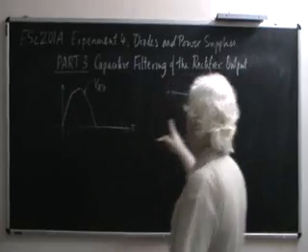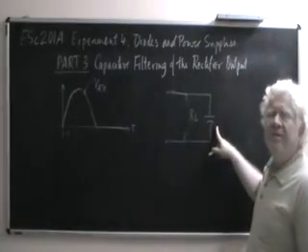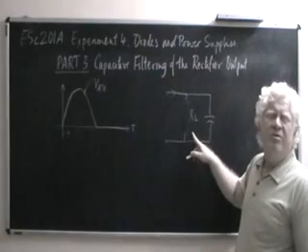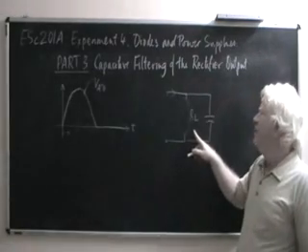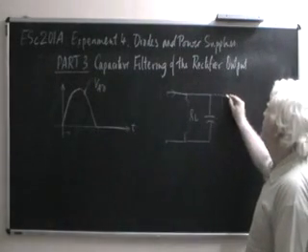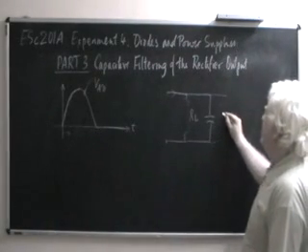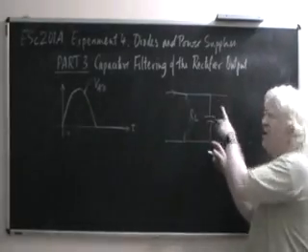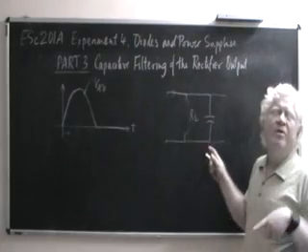The capacitor, having been charged up to this point, and under the assumption that the load resistance has been removed, has no means of discharging. So the voltage across these two terminals remains at the peak value because the capacitor has no way to discharge.